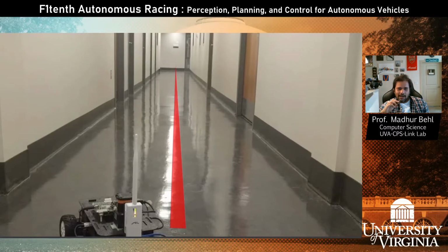We want our car to be in the center line of this hallway. So we define the left or the right distance away from the wall. And then the PID is going to look at the A and the B rays. It's going to compute its future projected error and use a proportional derivative controller to keep us on the track.